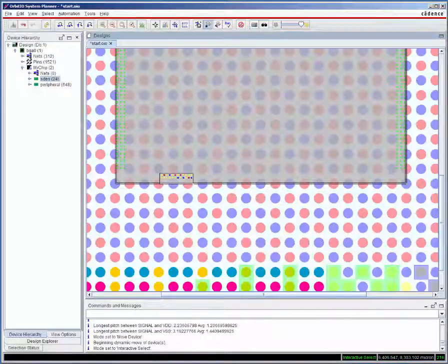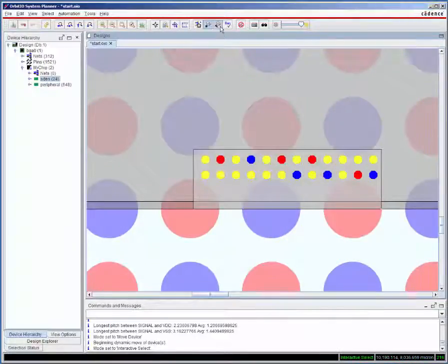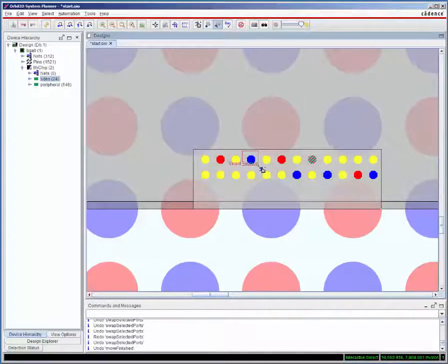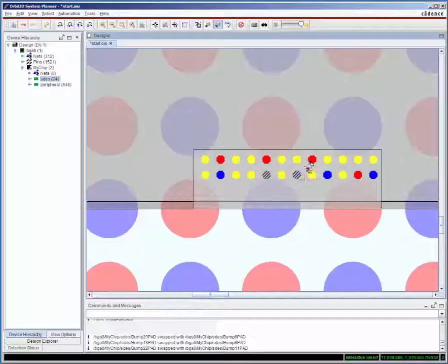I move the pins, then I use pin swapping to rearrange the personalities as needed. The LEF technology file defined the manufacturing grid as 0.005 microns, and as I move the pins around, they are snapped to this grid.